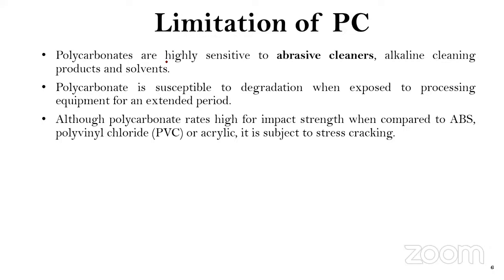These polycarbonates are highly sensitive to abrasive cleaners. What do you mean by abrasive cleaner? Suppose you have a PC window placed at your home; there you should avoid alkaline cleaning and some organic cleaning solvents.